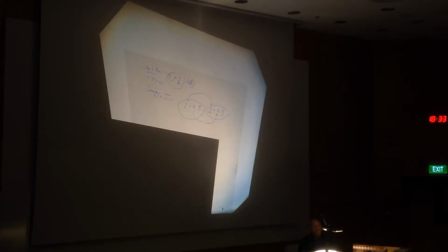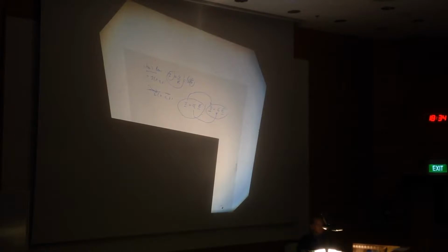And later we shall see that if we know the capacitance of a conductor, we can immediately find the corresponding resistance or conductance of this leaky capacitor. You have a capacitor that's leaky, meaning that the dielectric is not perfect. There is a small amount of conductivity. So when you pass a current, in addition to creating a capacitance, you can also create a small resistor of some value.